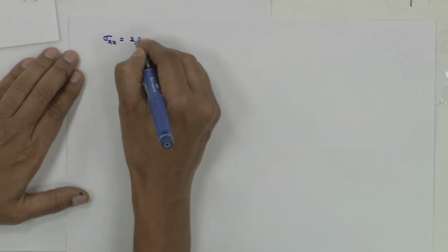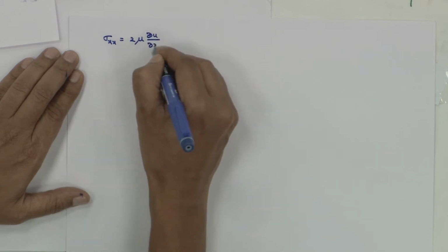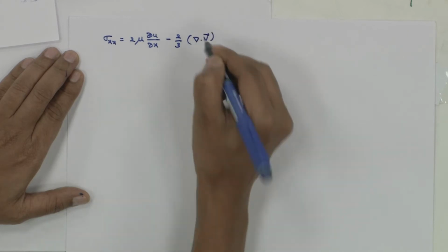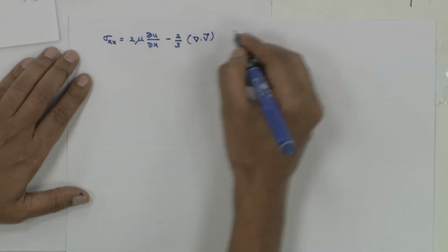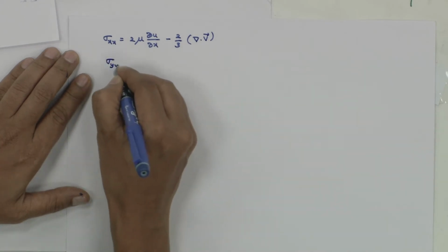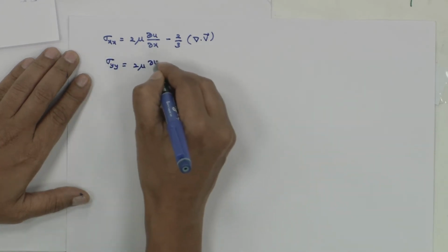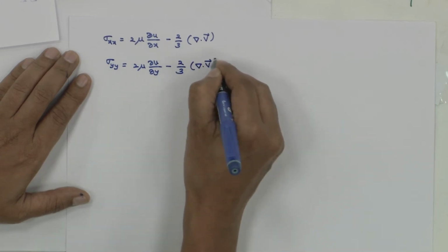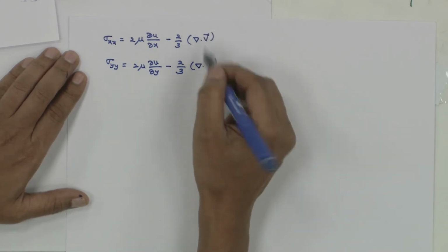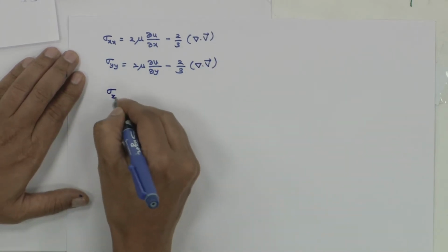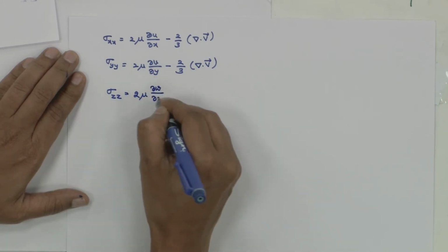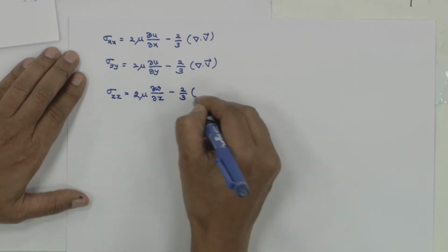That is sigma xx equal to 2 mu del u by del x minus 2 by 3 del dot v, and sigma yy equal to 2 mu del v by del y minus 2 by 3 del dot v. All constitutive equations I am writing, I may be using only few of them, but we are going to derive in the next few modules. And sigma zz equal to 2 mu del w by del z minus 2 by 3 del dot v,